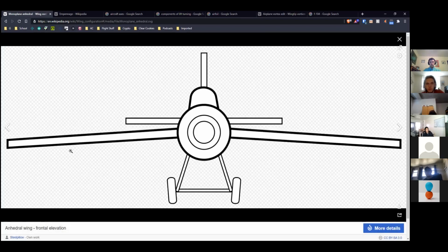The opposite of that means that if you roll over, then the wing will tend to exacerbate that roll. So there's not really that many planes, especially small like this or with low wings, that have anhedral, but most of the anhedral planes that I've seen are high wings, because you're already getting that effect of hanging the fuselage under the wings, which creates some stability.